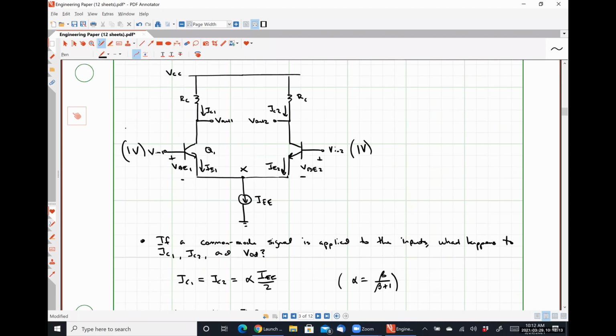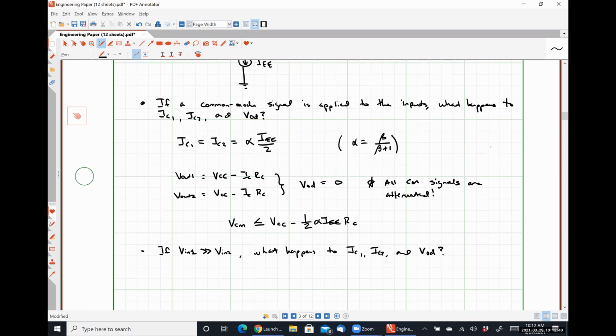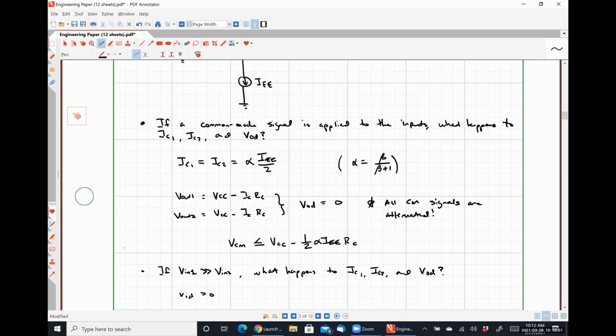All right. I think in the textbook, they describe this condition effectively as if we left this guy at +1 volt, but we moved this guy to +2 volts. So in this condition, our differential voltage VN1 minus VN2 is now positive, right? And so let's start with something real easy. We weren't specifically asked about it, but VID is greater than 0. This will be useful to us later on, right?